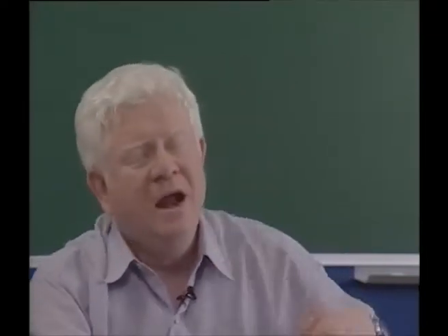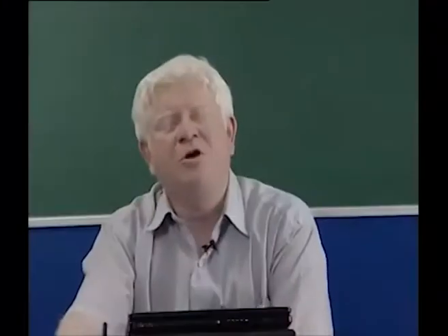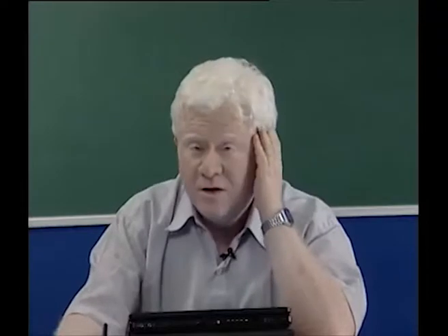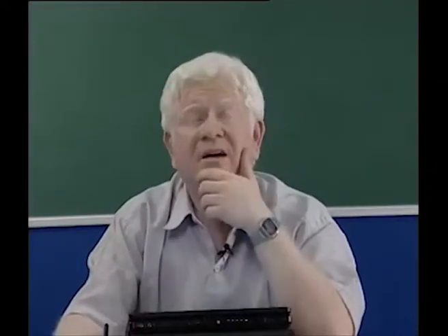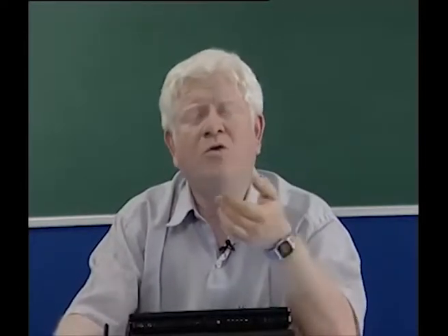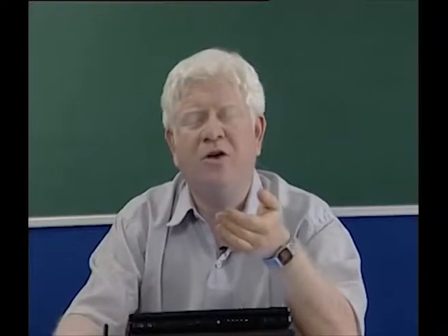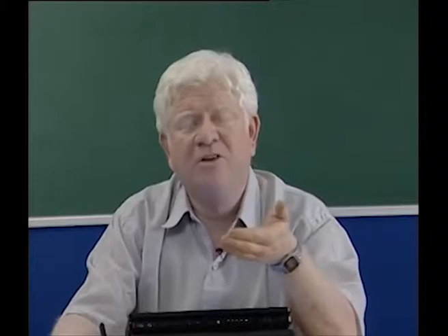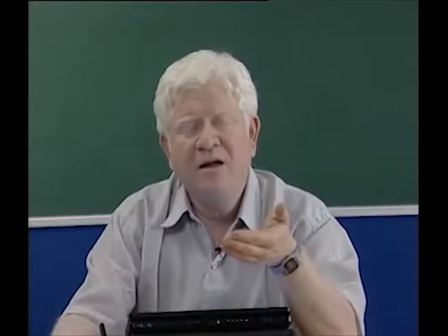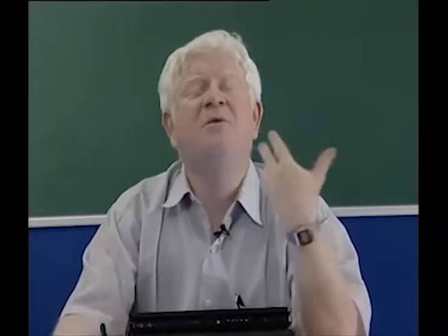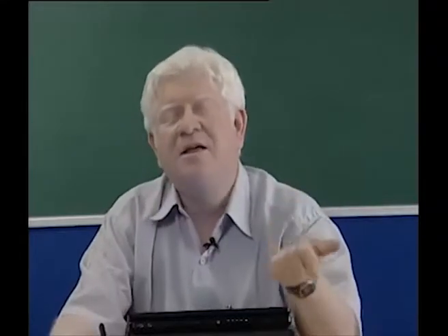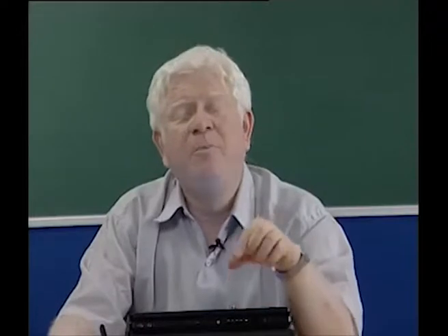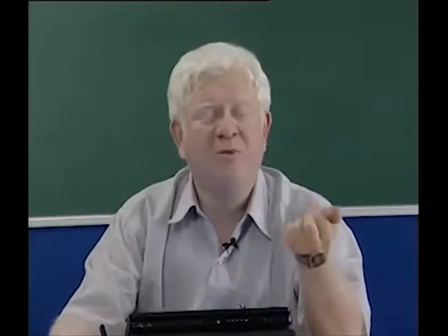You could go ahead and actually derive the impulse response, which could also look causal or anti-causal. The fact therefore is that what you want to do depends upon your choice, pretty much like the case of the auxiliary conditions, where it was additional information about the physical system that helped us to pick the correct solution out of possible solutions.